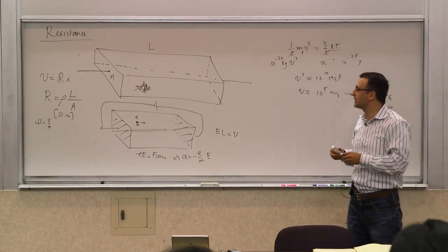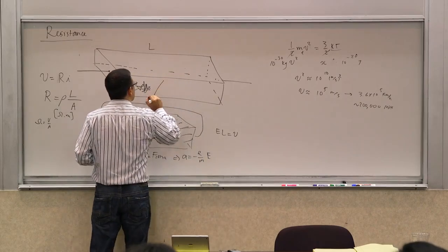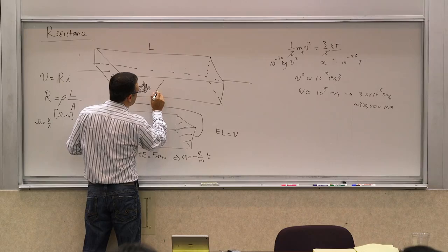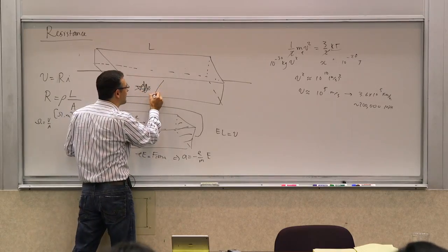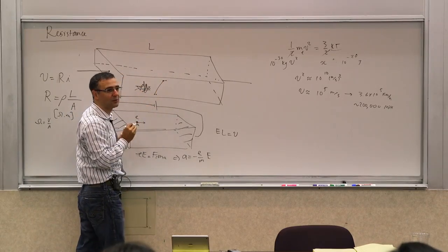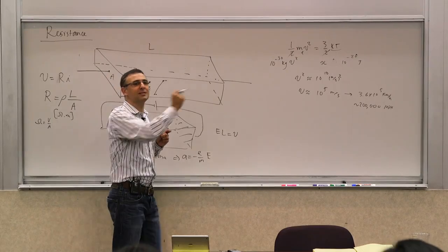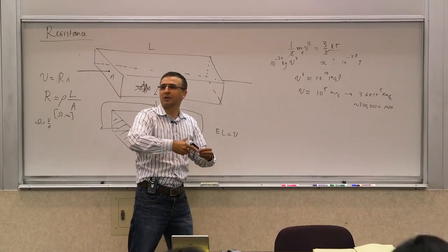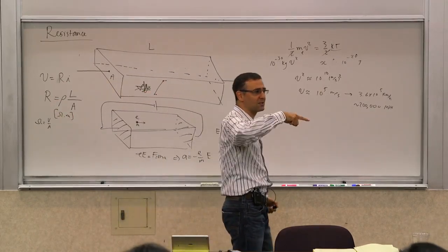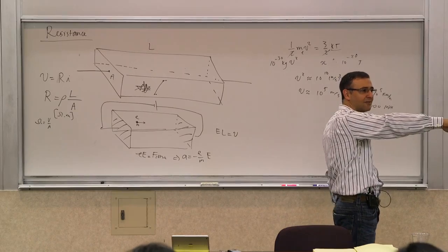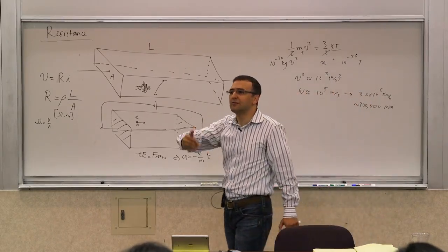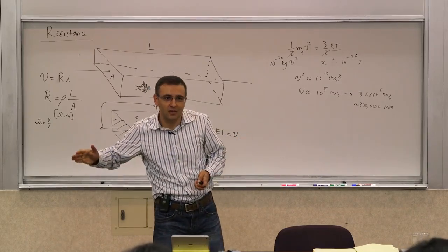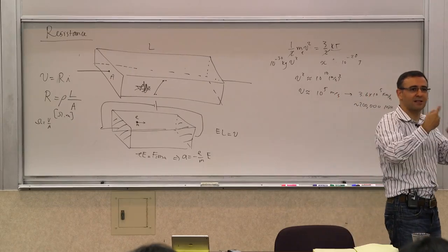When you apply an electric field, what happens is that, in between these collisions, they feel a little bit of an electric field and start moving a little bit, changing their velocity vector a little bit, accelerating, meaning that the velocity vector gets a small component added due to the electric field. But as soon as they hit something, that gets randomized. They bounce around, they go in a different direction, so that component of the velocity is not pointing in that direction. Since they're very frequently colliding with the lattice, they don't get time to accumulate this velocity. It just constantly gets randomized.